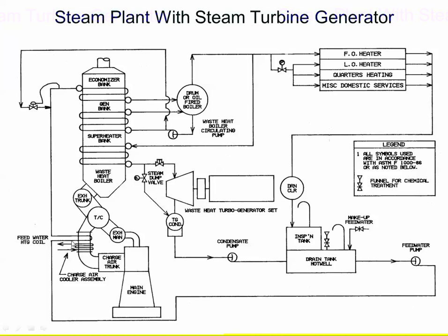So I'm doing waste heat recovery here, plus I am bringing up the temperature, so the temperature will be high enough to prevent getting into trouble from acid formation in high sulfur fuels. In this case, they're still a little bit worried about that. So what they're doing is they're taking some of the hot water and feeding it back into this loop here after the circ pump, and it's temperature regulated to maintain this. If I'm running at low loads and this is not high enough temperature, at low loads they would feed in some hot water to prevent the acid formation.